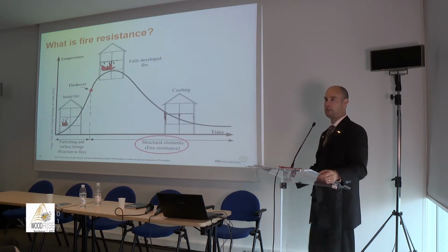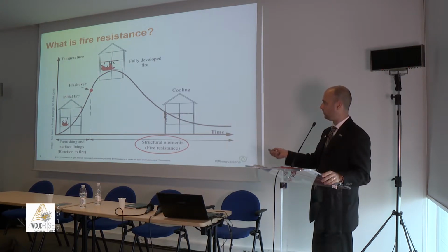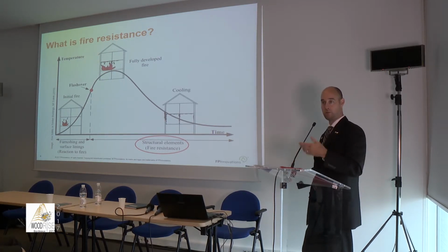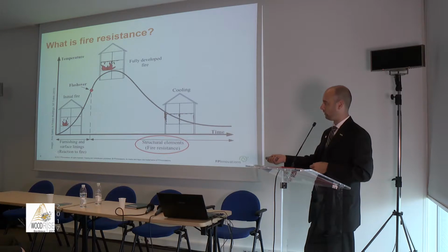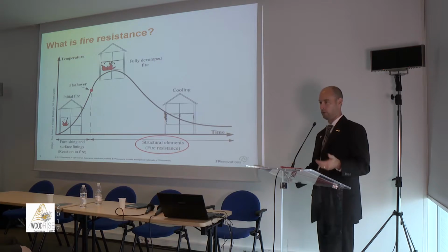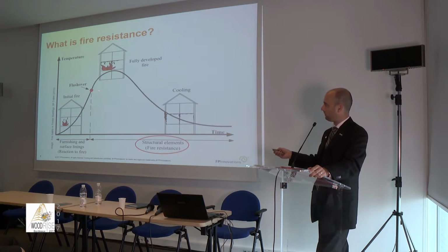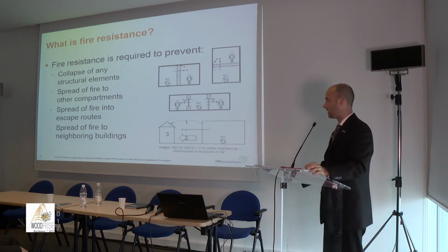What we're trying to achieve with that concept is basically aimed at getting into the design within that phase here. We had a previous talk on how to reduce the ignition or flammability of the product. Then that goes with the reaction to fire in terms of the European classification. In North America, it would be the flame spread rating that we evaluate differently. Otherwise, in a standard fire development, you have the flashover that occurs at some point, and then that's where the structural fire resistance comes in. So there are many aspects to it.